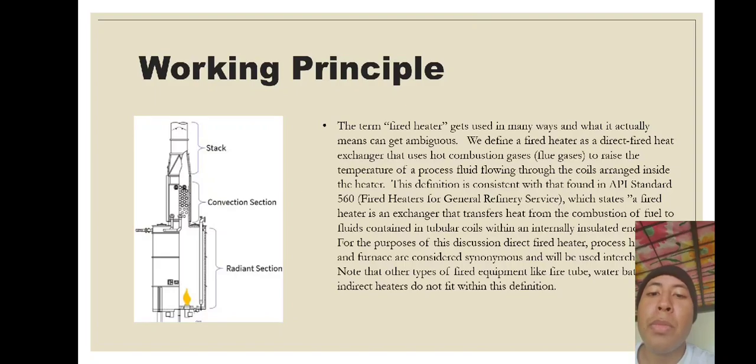get ambiguous. We define a fire heater as direct fire heat exchangers that use hot combustion gases, flue gases, to raise the temperature of a process fluid flowing through the coils arranged inside the heater. This definition is consistent with that found in API Standard 560, which is fire heaters for general refinery service, which states a fire heater is an exchanger that transfers heat from combustion of fuel to fluids contained in tubular coils within an internally insulated enclosure.